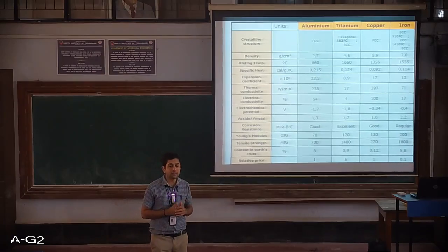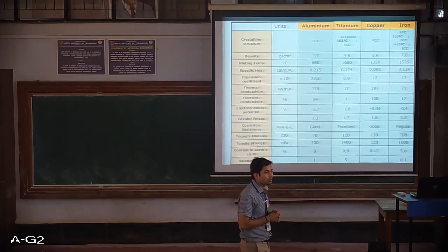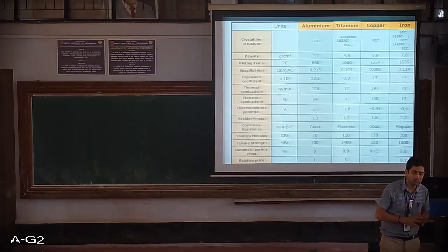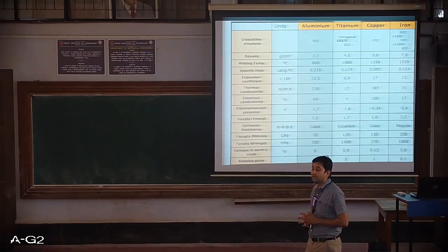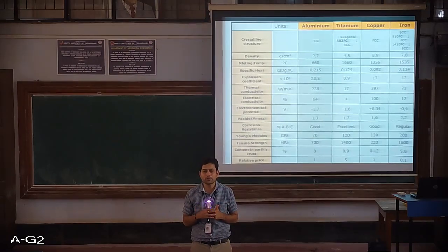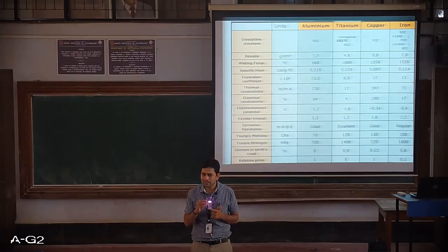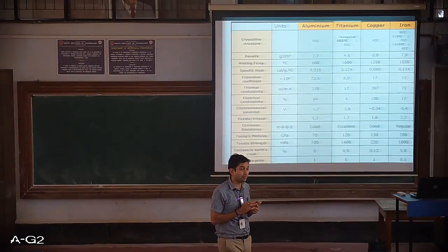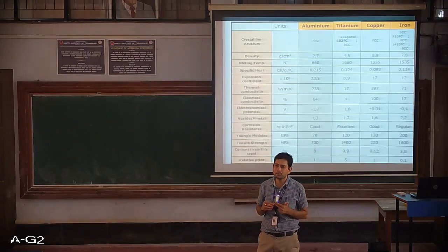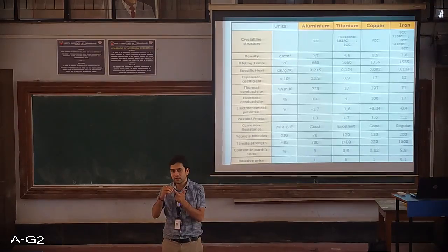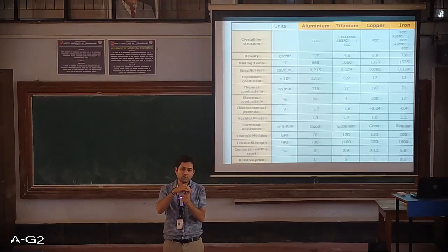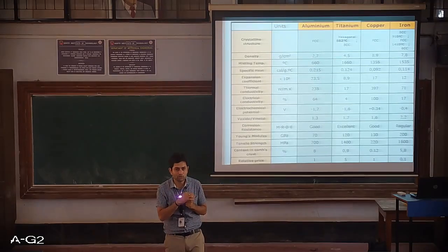So the next discussion, in the next class, would be only about material testing: how to test a material, and for each type of test, what are the important things you should know. In particular we are going to discuss the tensile test, which is widely done in the world to evaluate the properties of metal. We will discuss the compressive strength test, which is slightly less used. We will discuss the hardness test. The hardness test is the most important, widely used and most easily done test to evaluate the mechanical properties, and there is a relationship between the hardness test and the tensile strength of the material. So just by doing the hardness test, you can evaluate the tensile properties of the material also. That we are going to learn.